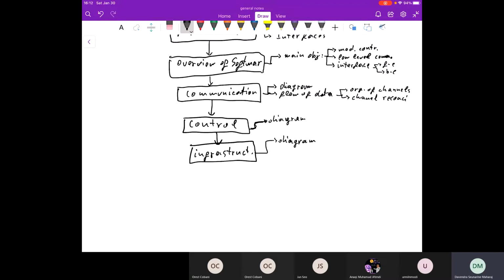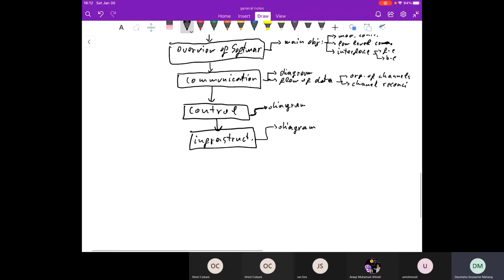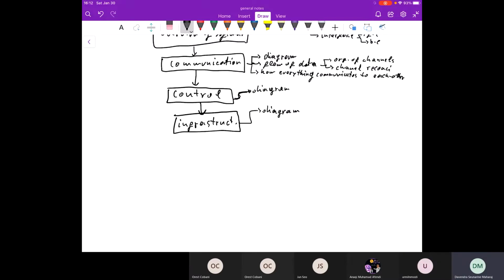We're going to show how the data flows and why the communication system brings the active components together. For example, we will know what happens in the brakes, the batteries, the motors, the inverter. From there, it's easy to flow to control, because with the publish-subscribe model, all of the data publishes to the Odroid. In control, the diagram is essentially the Odroid and the controller, or the state machine.